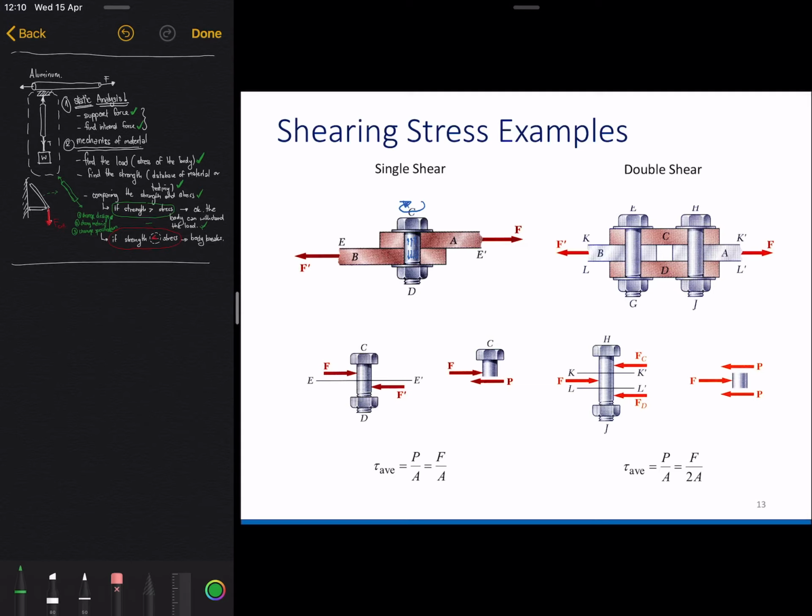and the material will try to shrink. In this case the bolt will be clamping these two parts. So here we will have a force from the bolt pretension. And when we have bolt pretension like this, what we have learned previously is about the shear stress. What is the function of the bolt? Normally we use it for clamping two materials or two bodies together.